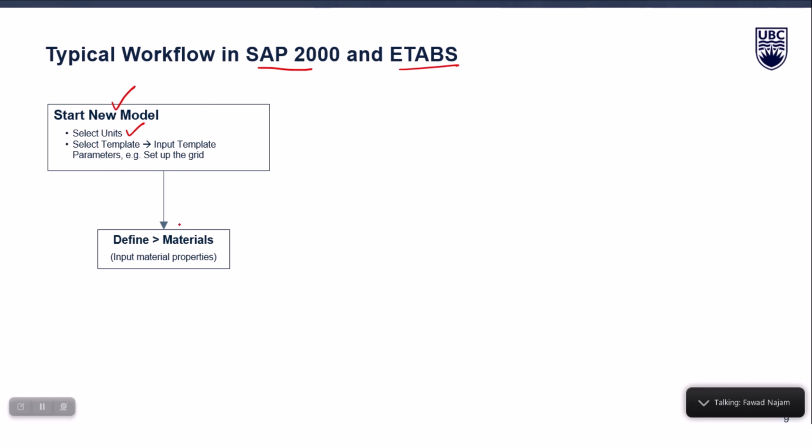In our case, which is a simpler case for frames and beams, for example, the material property of concern will be elastic modulus, right. So, elastic modulus we will be defining for all the materials which our beams or frames will be made of. Then we will define cross sectional sizes, like beam size if it is rectangular or I shape or any other shape, and what is the size of that beam. This information will allow the program to determine capital A, the cross sectional area, and the moment of inertia, right.